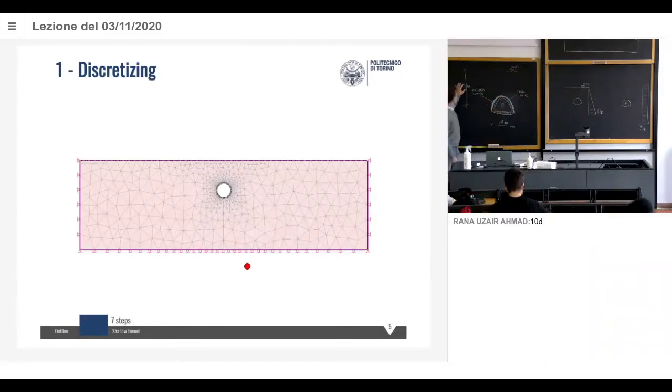I said, well, let's assume that this is 100, and so we have 140. We go above that. Well, this is not an issue. If we are assuming a deep tunnel, it means we have to go like this. We don't care how big the model is, because the hypothesis is that the state of stress is constant. So it's not an issue that we go above that, because it's just our model of reality, our representation of reality. We assume that the state of stress is constant, so we need the boundaries to be far away enough not to influence what happens here, but then it's not an issue. They go beyond the real boundary.